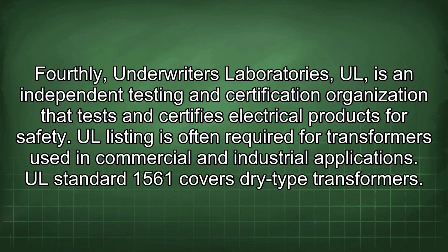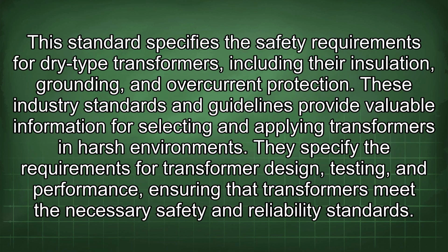factors. Fourthly, Underwriters Laboratories (UL) is an independent testing and certification organization that tests and certifies electrical products for safety. UL listing is often required for transformers used in commercial and industrial applications. UL Standard 1561 covers dry-type transformers. This standard specifies the safety requirements for dry-type transformers, including their insulation, grounding, and overcurrent protection.